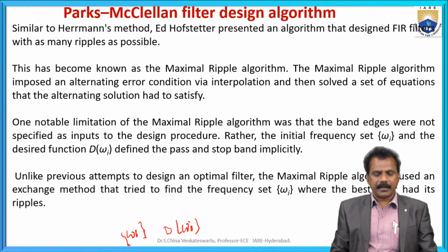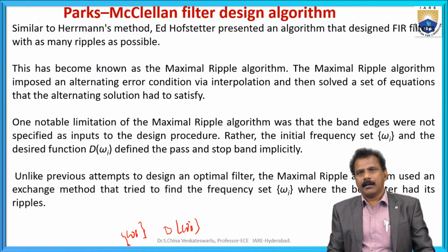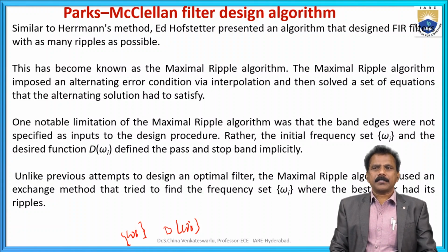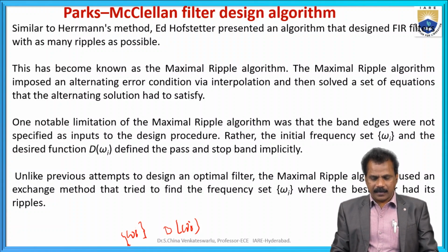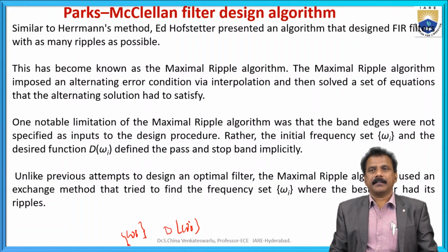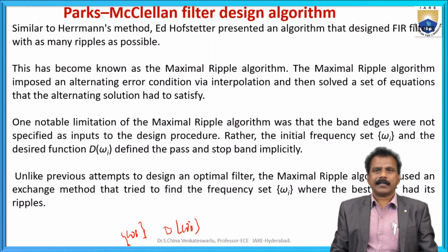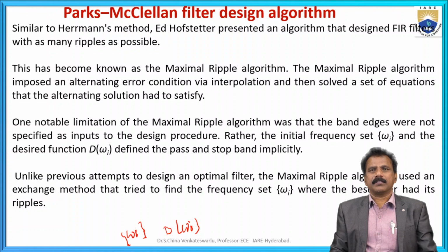Unlike these previous attempts to design an optimal filter, the maximum ripple algorithm used an exchange method, trying to find the frequencies omega i where the best filter had its ripples.